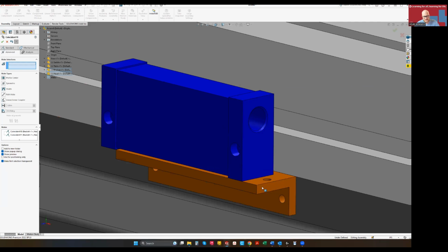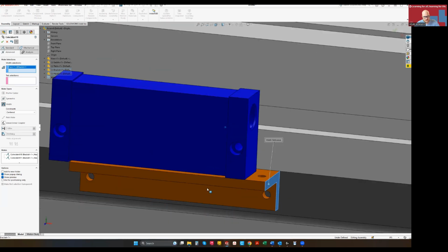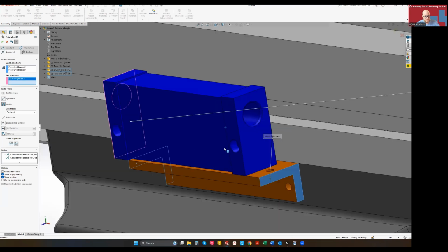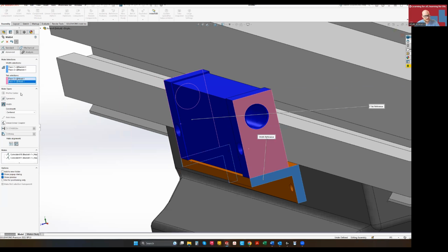In this case, I think I like doing width mates. I use them a lot. And I just like that profile center. I use the profile center quite a bit in my professional drafting. So I think even though they are maybe a little bit more advanced than we would generally get to in this class, in terms of best practice, that's likely what you would be using in this situation. Because you want to keep the model as simple as possible.